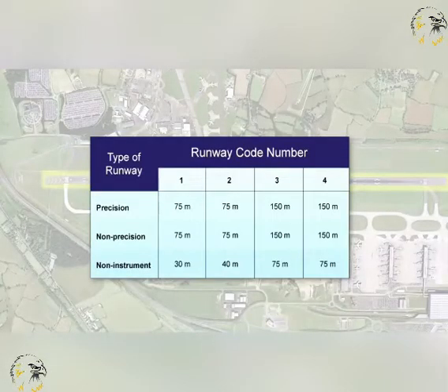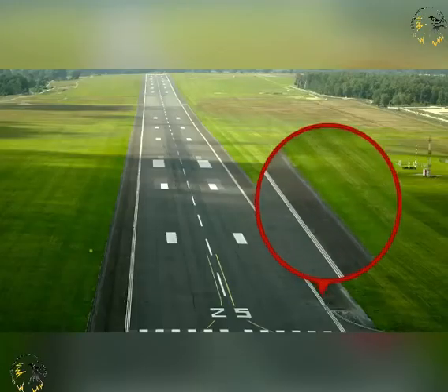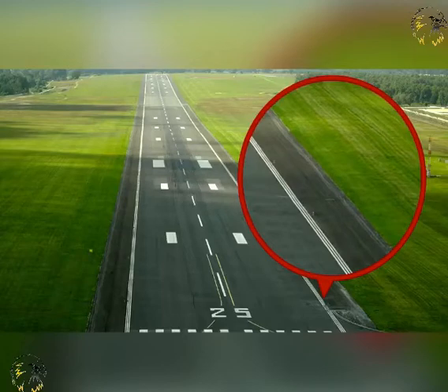The width of the runway strips are to extend, when practicable, laterally on each side of the centre line of the runway and its extended centre line, through the length of the runway strip to a distance as defined here. Code 3 or 4 instrument runways shall have an area 75 metres either side of the centre line, graded so that aeroplanes which the runway is intended to serve shall have an area that they can safely run off the paved surface onto in the event of an emergency. For runways coded 1 or 2, then the distance will be 40 metres.